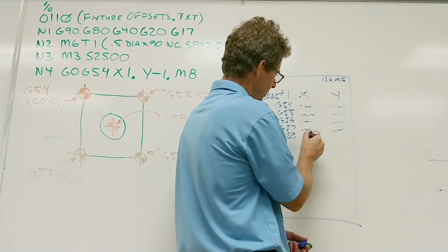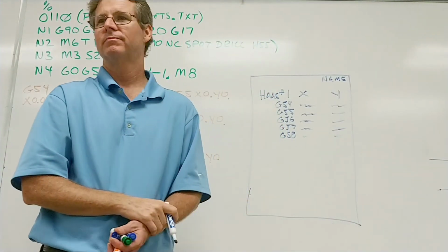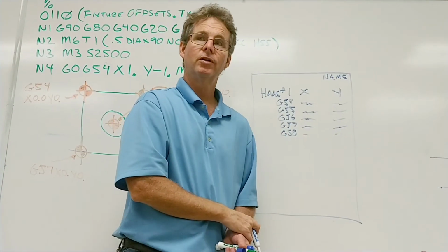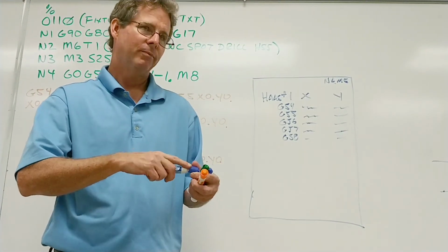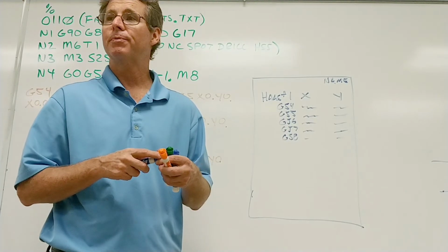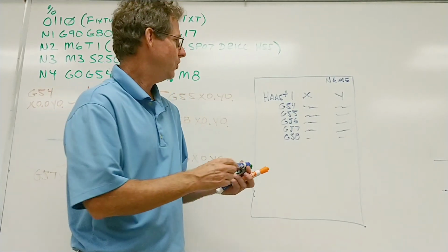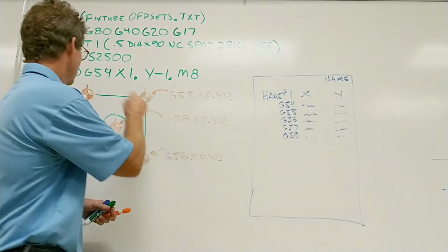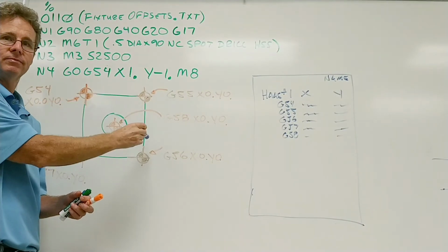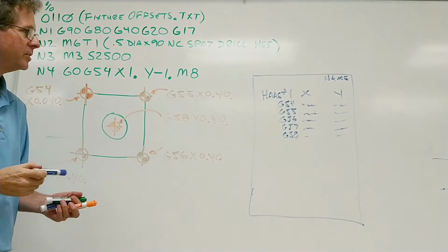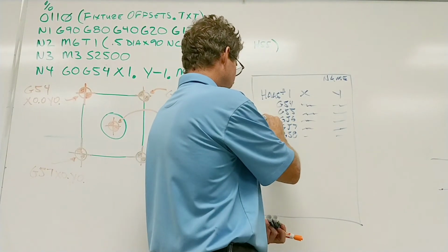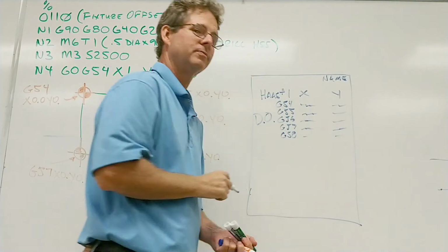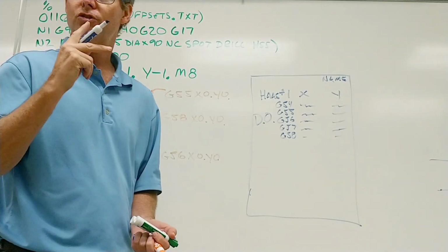You might want to indicate the corners and not record yet, and then have me come over, because I'm going to show you how to put an MDI program into the machine that will physically move to each corner of the block so we can check it. Then once I see that you have it there, just like the startups, I'm going to put my initials right there. You're going to do 2 Haas's.